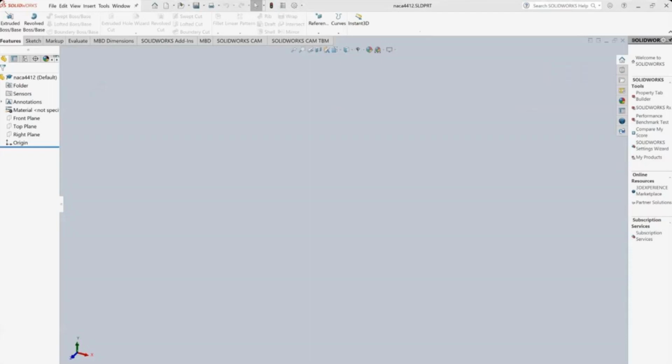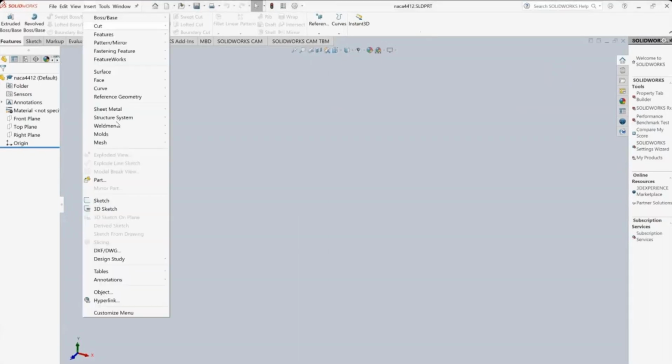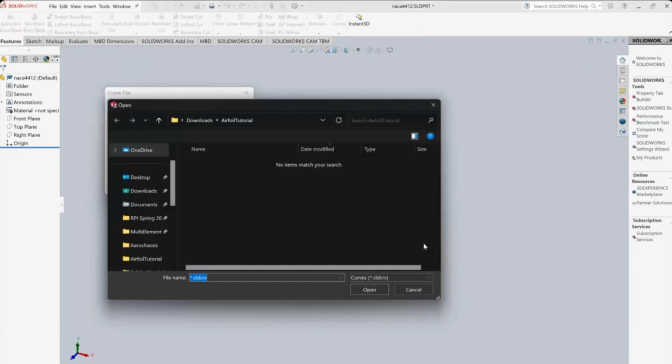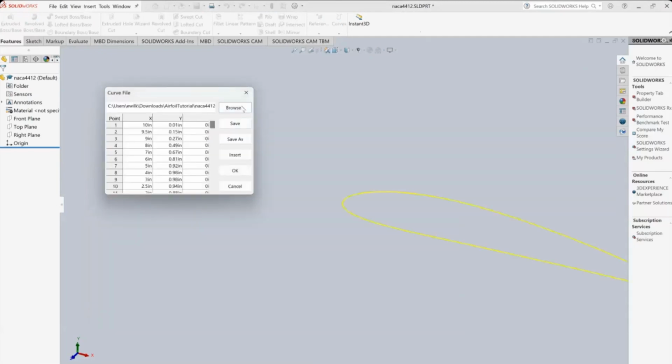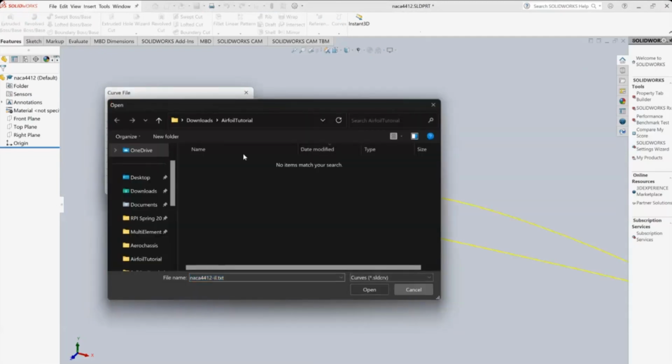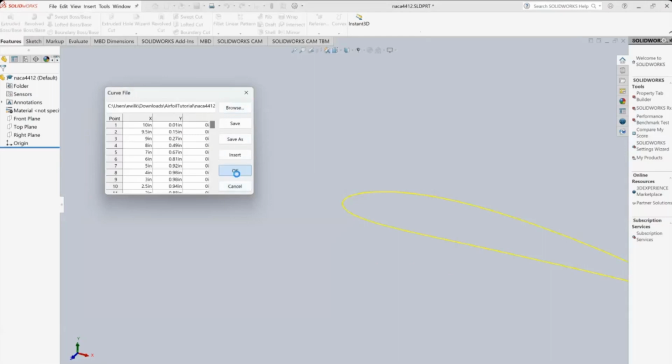So now we are on to SolidWorks. So I'm going to show you how to do the two methods of CADing airfoils inside SolidWorks. So here we are with our part. We're going to go to Insert, Curve through XYZ points, Browse, switch to text file, and select the text file, and it will make our airfoil. Nope, don't do that. Okay.